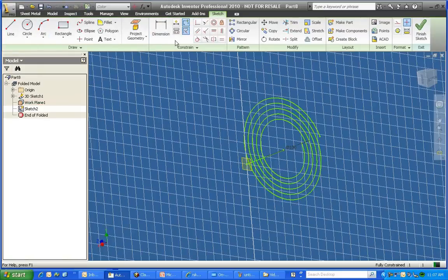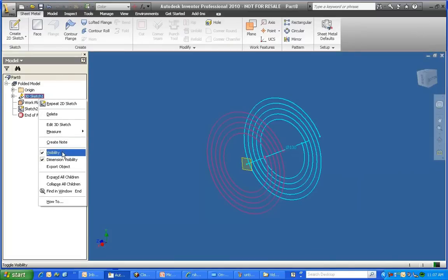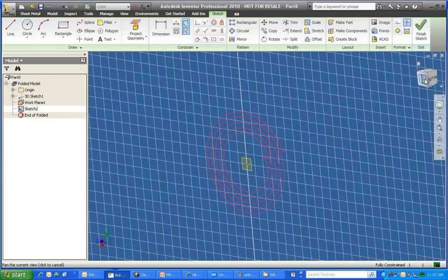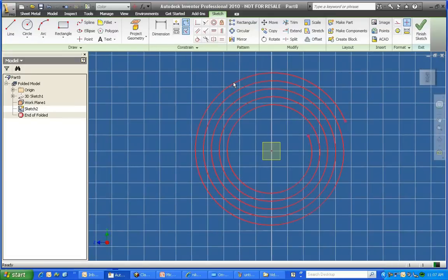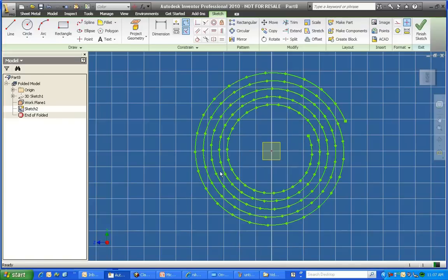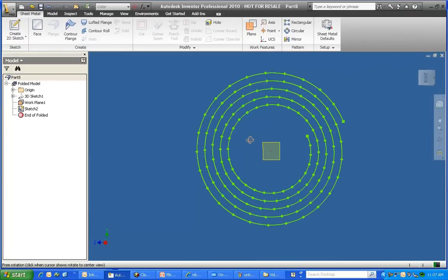I use the projection to turn my 3D spiral into a 2D sketch. At this point the 3D sketch is no longer needed. And in my 2D sketch I need to do an extra post-processing operation to make it work, and that is really key here. I need to break the link with that 3D sketch, otherwise the development of that spiral won't work. So I use break link, it adds extra nodes, and from here on it's cruising really.